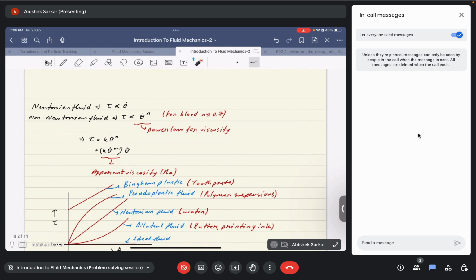So to remove this proportionality sign, we use a proportionality constant, say k. Then we do certain mathematical manipulation so that we can write tau in terms of a single power of the shear strain rate. This term k theta dot to the power n minus 1 is considered to be the apparent viscosity. There is no physical meaning to this term; it is just a mathematical manipulation done so that we can correlate this expression to the other expression that we wrote, that tau is equal to mu times theta dot.